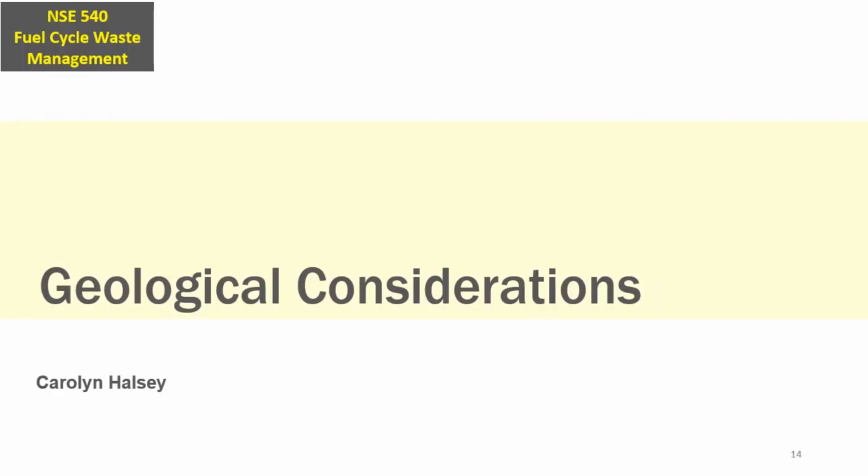Hi, my name is Carolyn Halsey, and I will be discussing the geological considerations related to radionuclide transport. This includes the physical and hydrologic characteristics of the rock media and the water and solutes that flow through it. The purpose of deep geological waste disposal is to delay the migration of radioactive material as long as necessary for the material to decay before it can travel to the biosphere. Geological and hydrogeological factors influence how these radionuclides migrate through the ground and water system and therefore must be considered.